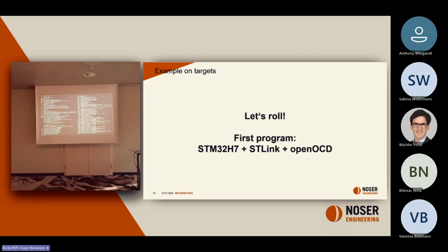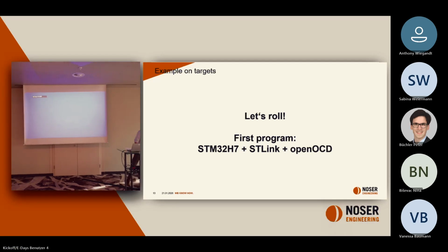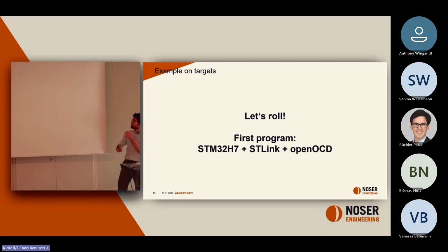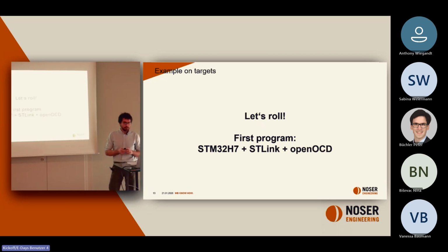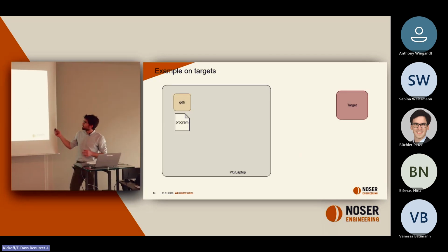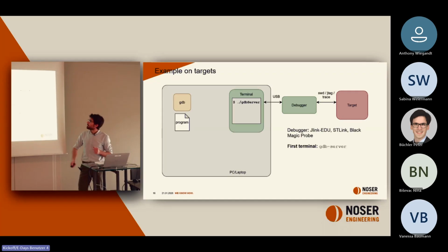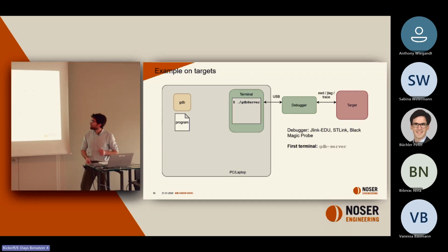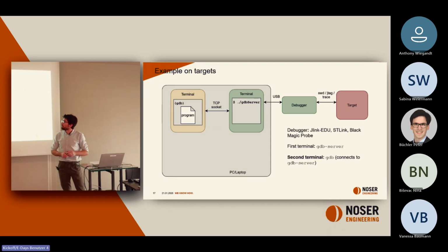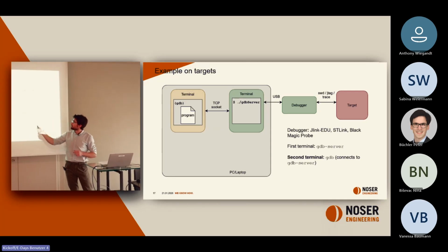Exactly. Now, to recapitulate, we had our target. We connected the debugger, which is already connected. We started the GDB server in the first terminal. We run GDB and we connected to the GDB server.